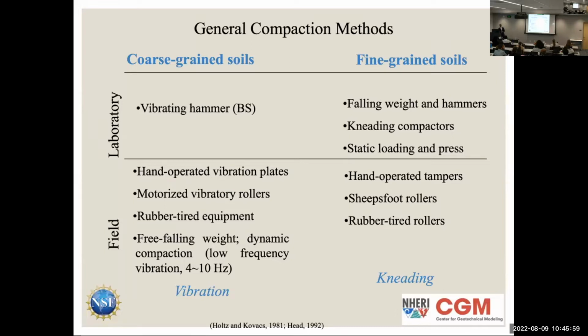And since we're using fine soils, the best way for us to compact it would be with a sheep's foot roller. Later down the line, as you saw in the introductory, I'm going to be explaining what kind of compactor we use, the whole process with that, and how difficult that was, but that's for a different time.